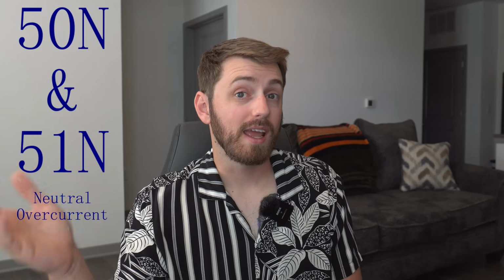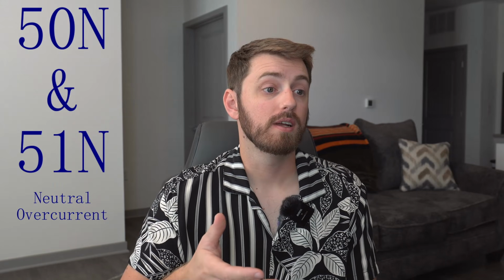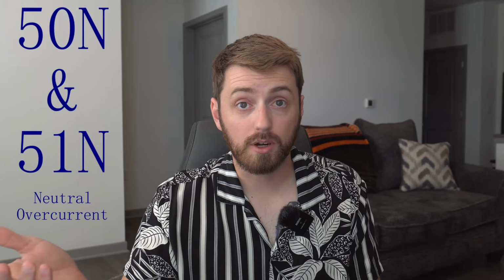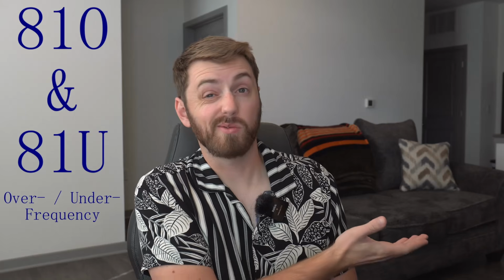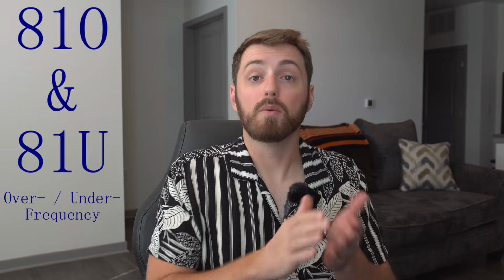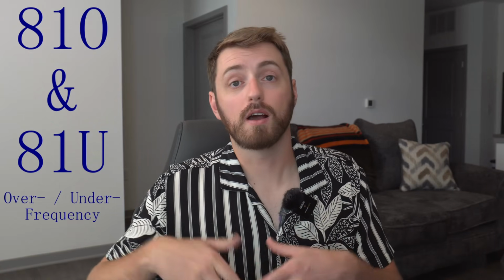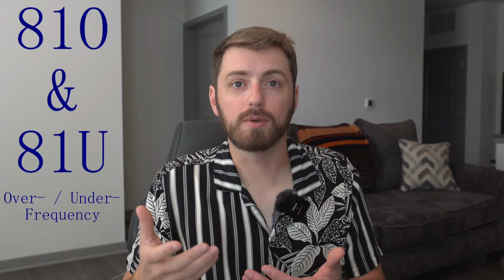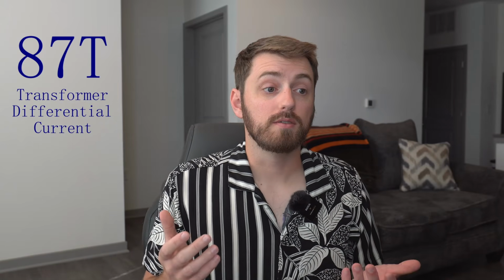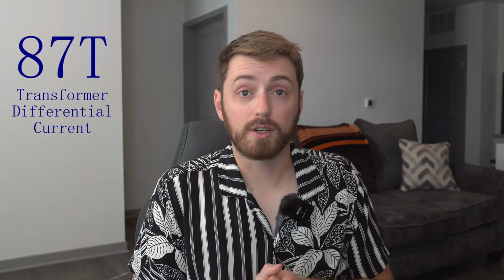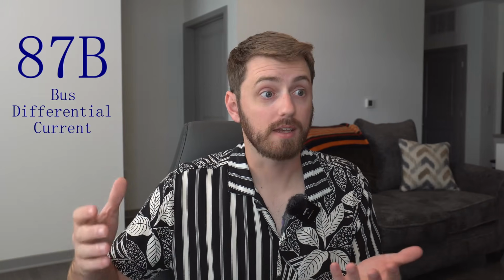50N and 51N are really common ways to describe neutral overcurrent. 81O and 81U are often used. I actually don't call them out this way on the 751, but I do want to talk about it real quick. 81 is for frequency. 81O is often the quick hand that we use for describing over frequency, and 81U is for describing under frequency. 87T is a term generally used for transformer differential, and 87B, 87 is for differential, 87B would be for bus differential.